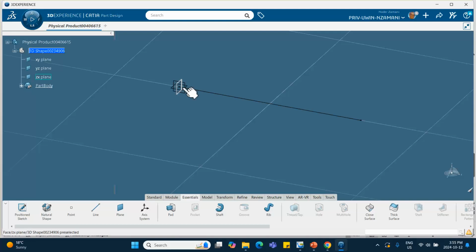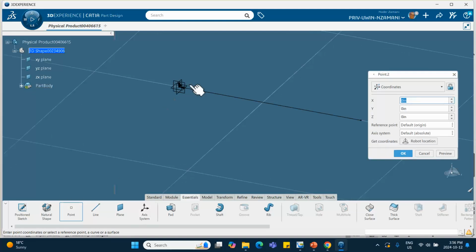Now, in general, if you have a non-circular cross section, you need an orientation point. And it is also the case that for a general section, you need an orientation point, because otherwise it won't let you close that box. So I can do it now, or I can do it later. Either way. What I'm going to do is create my orientation point now. Otherwise, I have to come back here and create an orientation point. So I'm going to say a point. I'm going to make it off this. It has to be off that axis. It cannot be on the continuation of it, etc.